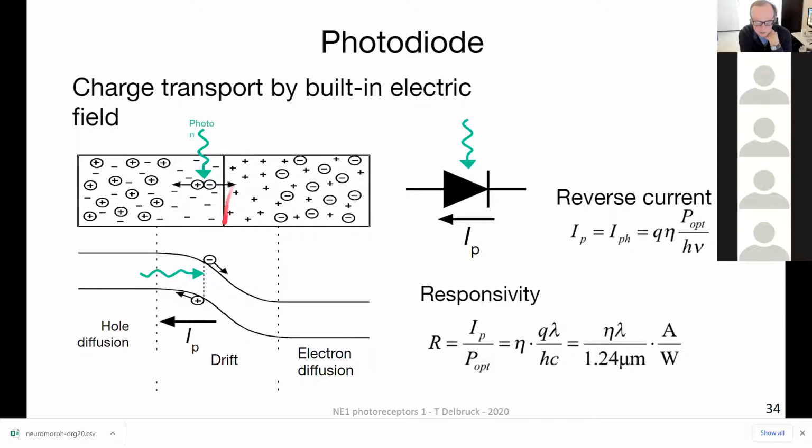And remember, when they come together, it forms a space charge region. Within that space charge region, it's depleted, so there are essentially no mobile carriers compared to the neutral regions outside. But within that region, there's a very strong electric field that builds up to a peak in the middle and then goes back to zero on each edge. That electric field is there to oppose the diffusion current. Remember, everywhere within this junction, the drift and diffusion have to balance each other.